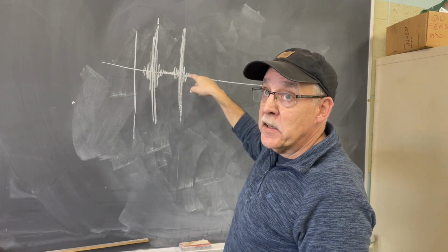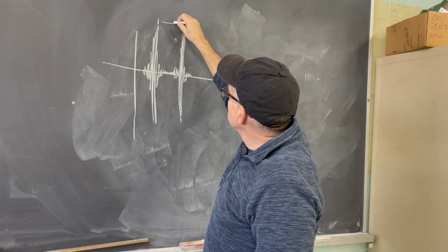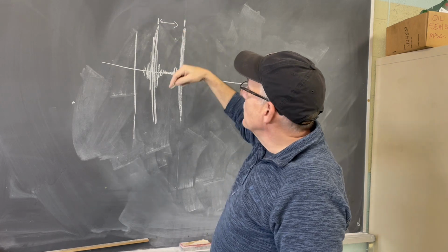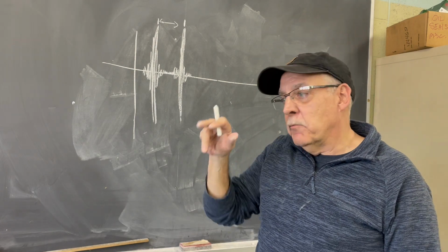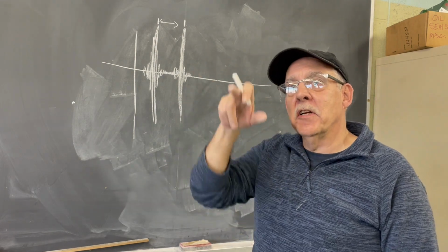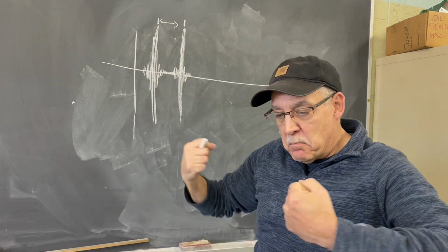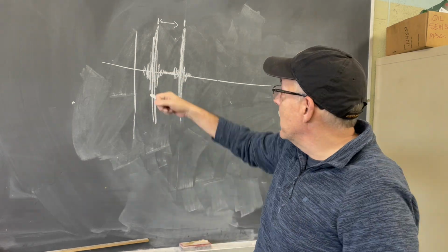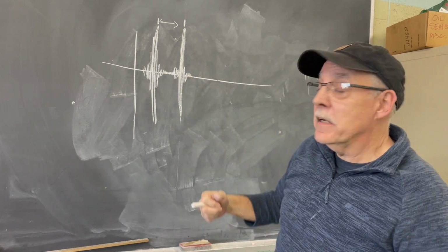They look a certain way in the waveform. So I measured the time between here, take that time, measure it, get a frequency, and if it was a broken gear tooth, it would be 1 times the frequency of the gear with the broken gear tooth. Every time that gear would go through the mesh, there'd be the big bang, because there's a broken tooth, and it would come out of the mesh, take another revolution, bang, take another shock.